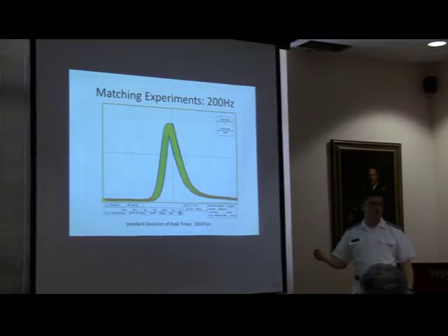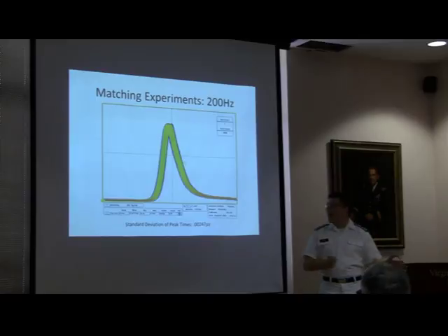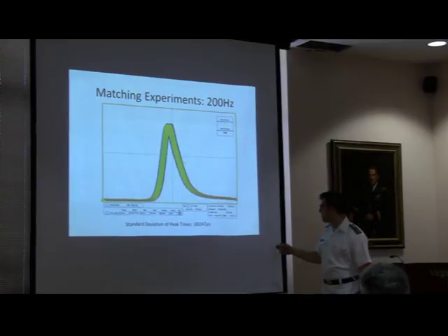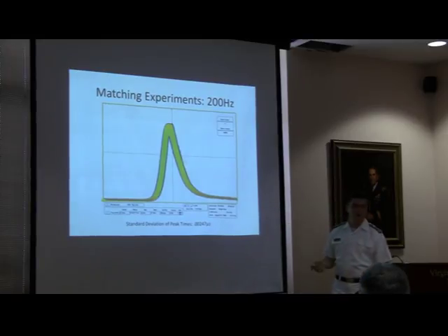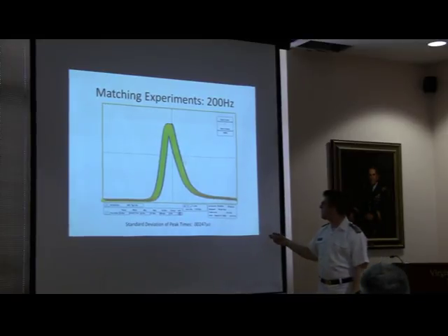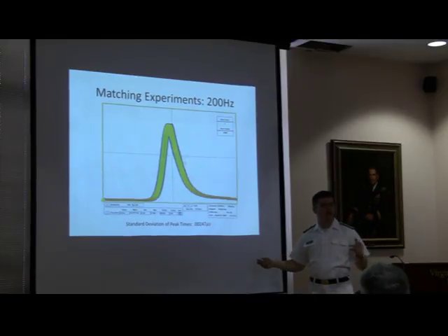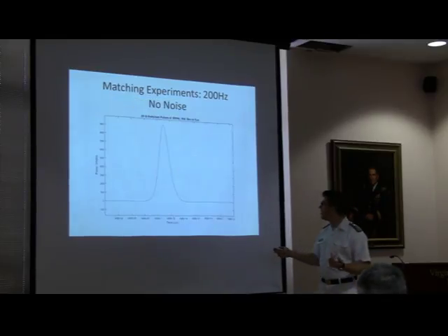Let's take a look at 200 hertz, another side of the scale. This starts off with a much lower spread, a much lower standard deviation, and a different shape up here with that horn being almost completely gone. And just look at that, much tighter spread, which we should expect, because remember, there is less deviation in the lower frequency because it has more time to settle, and so it's a little more accurate.